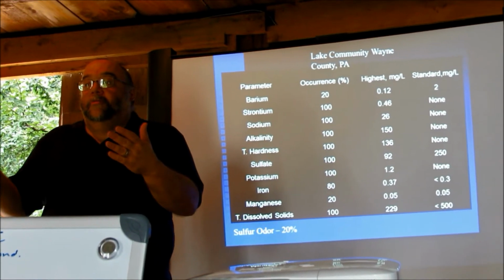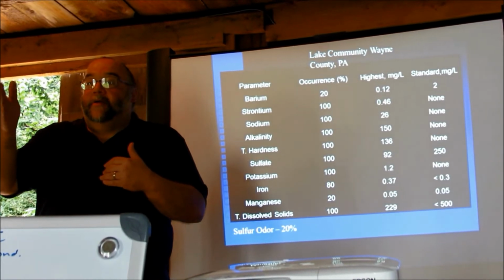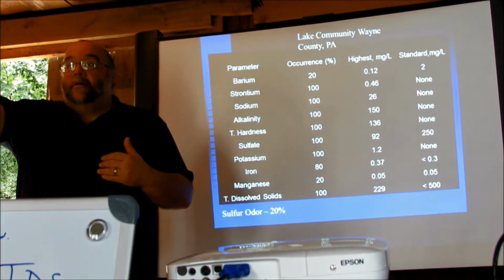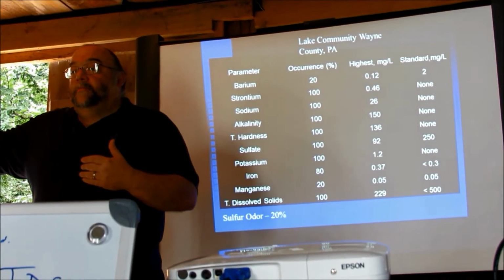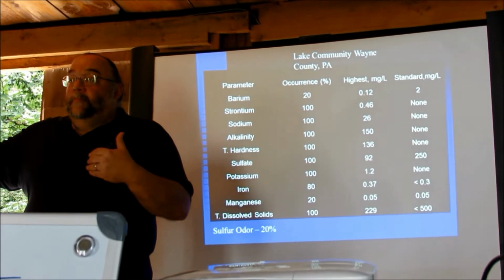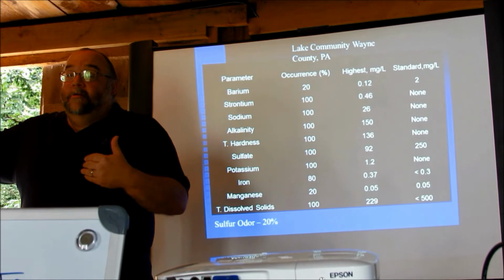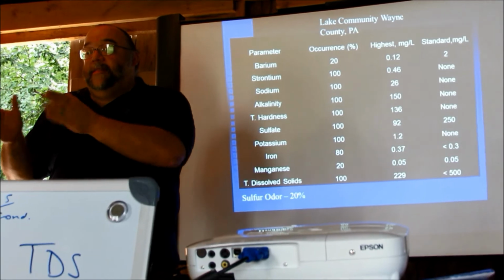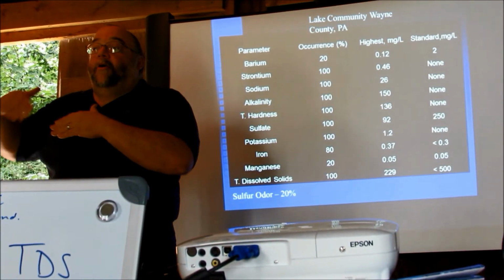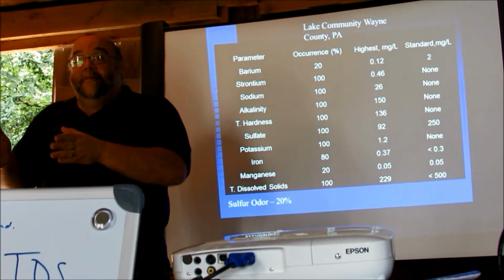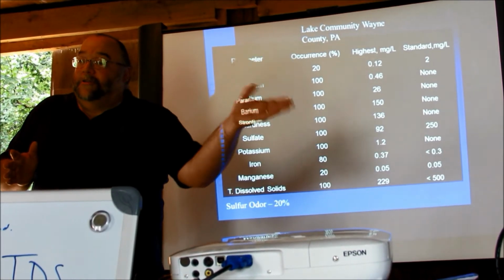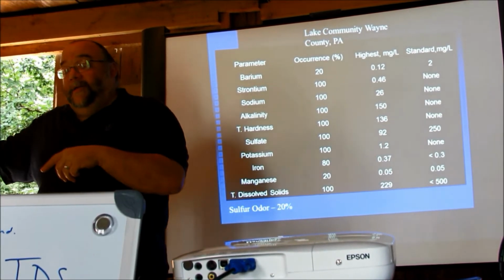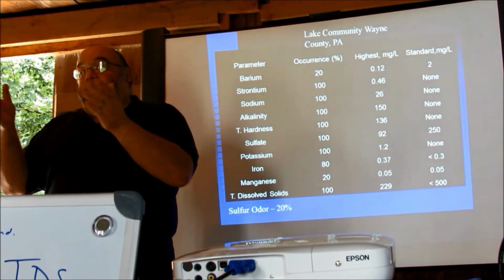That becomes a difference, because if you compare the meter set up for the stream to saltwater, you're going to underestimate the TDS in saltwater, all the time. You never want to underestimate on your worst case. If you want to overestimate, you always want to overestimate on the least possible concern. I always want to overestimate on fresh water. I don't want to underestimate my saltwater impacts. So that's another way of looking at it.